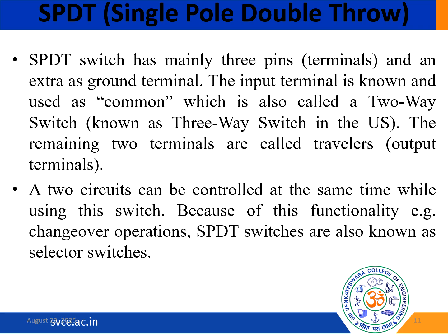Considering this SPDT, single pole changeover, and SPTT, we can call it single pole center off or single pole triple throw. SPDT is single pole double throw, where a versatile circuit selector is possible. This switch features three primary terminals. First, we have the common input. The central terminal is connected to either of the two outputs. That is the common input.